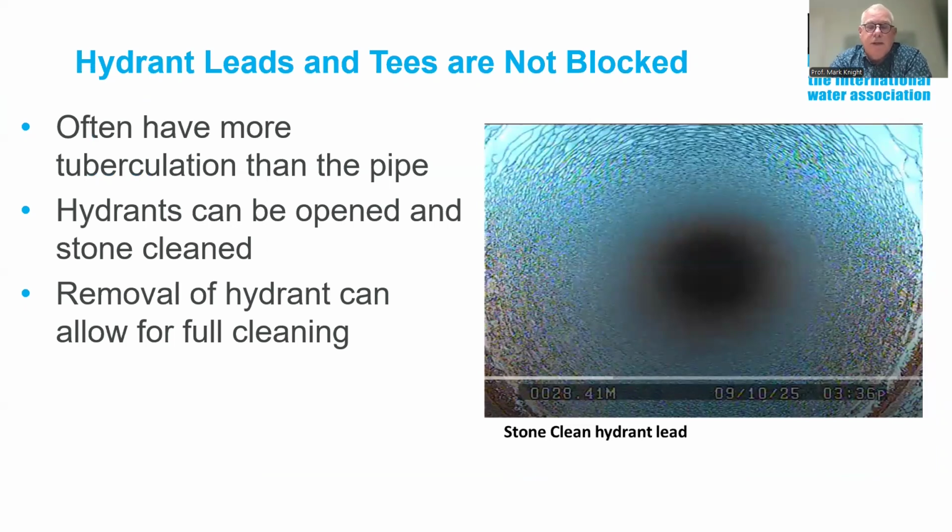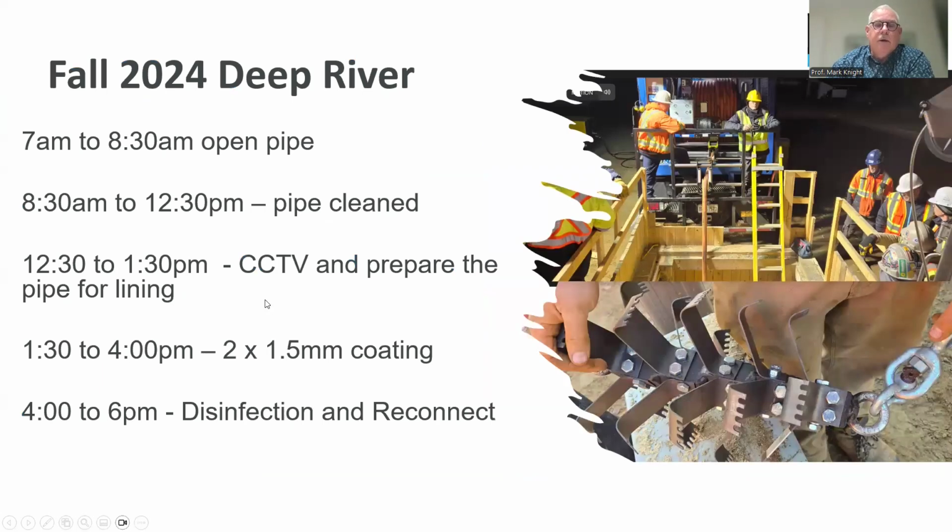We can also clean hydrant leads as well. We can't coat hydrant leads, but there's often more tuberculation in the hydrant leads. And you can just see the material sprays up on the inside of that hydrant lead and basically cones.